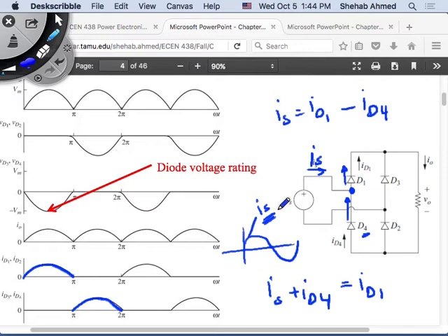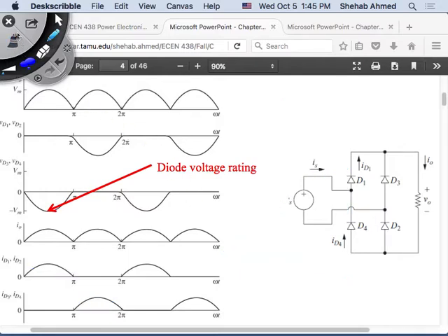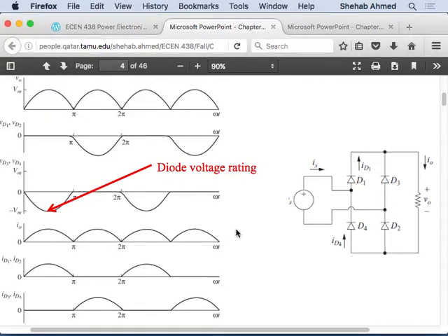So what is the power factor of this converter? Unity power factor, right? You have a nice sine wave that's in phase with the voltage. Yes, sir. So how do you use the source? Can you give us an example? How do I produce that? The next converter will do that. If you're going to draw something non-sinusoidal, then you're going to have harmonics. That's what the following one after it will show. Yeah, we will do that.